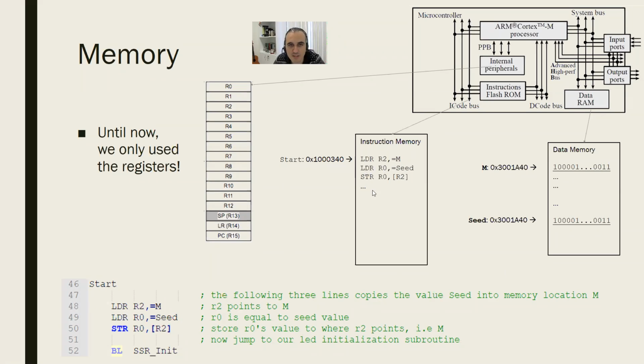Actually, we are kind of accustomed to this. We've also talked about the data memory. This is where we keep our data, not the codes, data. It's a different type of memory because it's architecturally placed somewhere else. Instructions are connected to the control unit of the microprocessor. Data is connected to the data bus and the input-output ports. You don't know what input-output ports are.